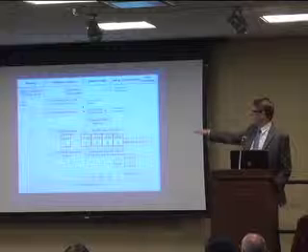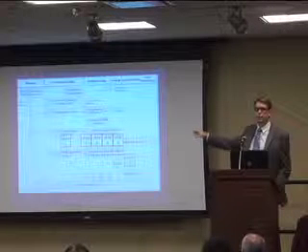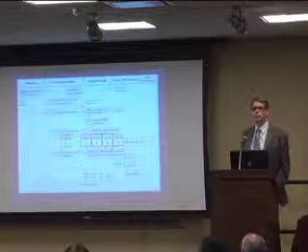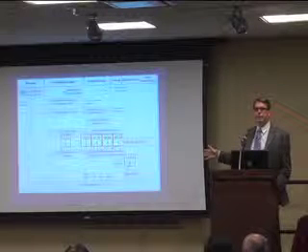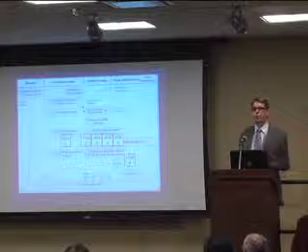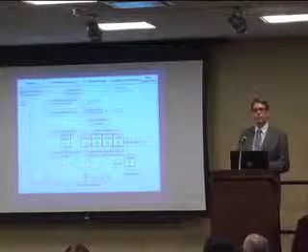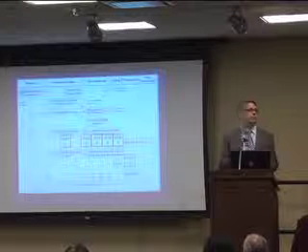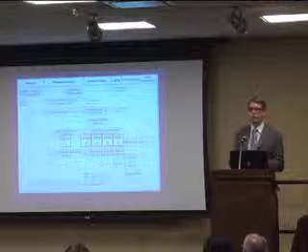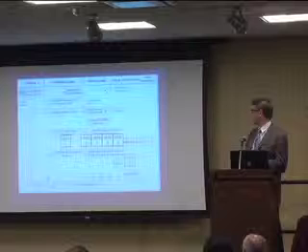So we're thinking around the design conference, there should be an update to the utility conflict matrix. Then maybe at 30% design, 60%, 90%. Whenever you meet with the utilities, typically, and whenever you have a chance to exchange information, to update the information that you received, and to come up with a new version.